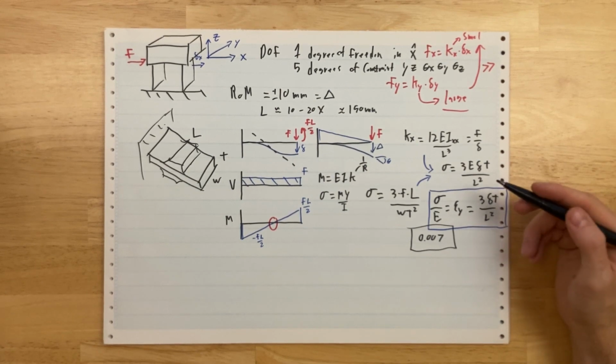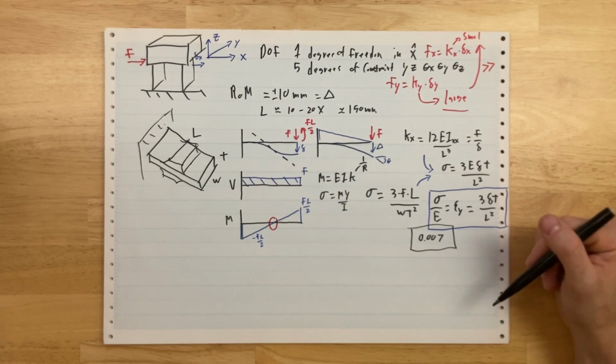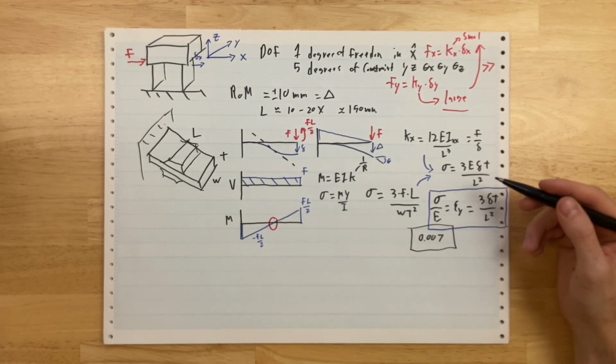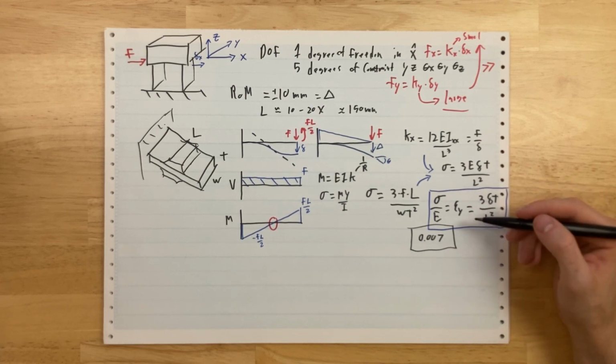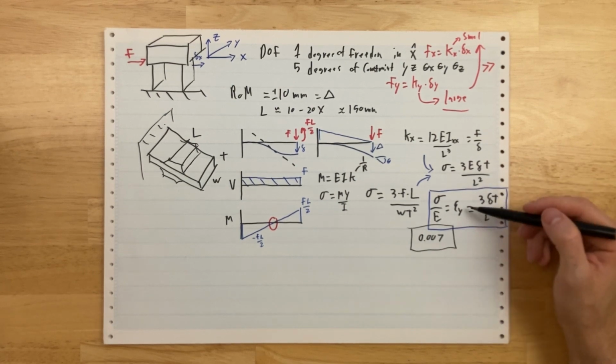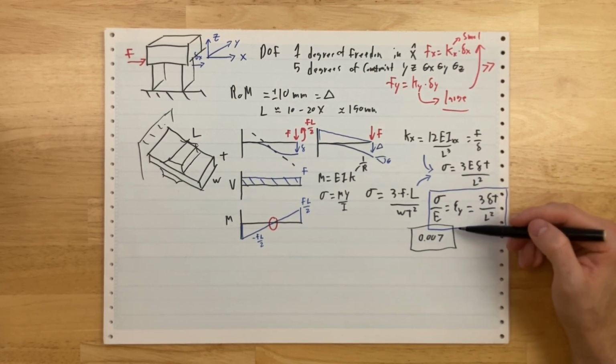Plastics go much higher, but their modulus is really low. They tend to be kind of soggy at high temperatures. They don't do that well. They're viscoelastic. And 7075 T6 is a lot cheaper and easier to work with than titanium and hardened steel. So if you just care about deflections, go with aluminum to make your life easier.